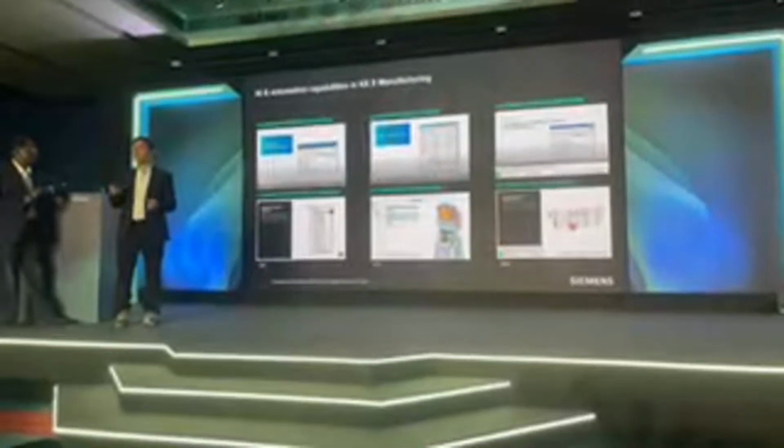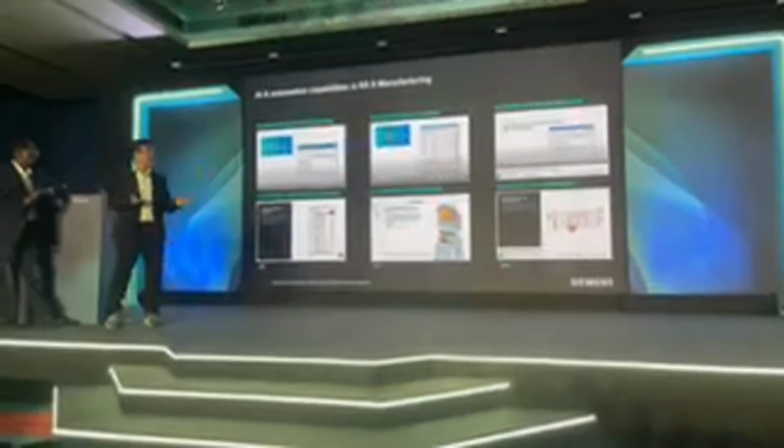What we're talking about here is AI and automation, in particular CAM programming. See what we have available: automation capabilities like AI-assisted operation creation, AI-assisted offset editing, and automated feed and speed. So when you are making a program, you don't need to put in the values; it automatically helps you set the feed and speed, and also the CAM prediction minibar. Whatever is AI-assisted, it will suggest some predictions in the minibar for what you will do next, so you don't need to search for the icons.